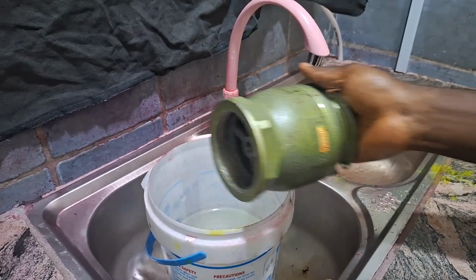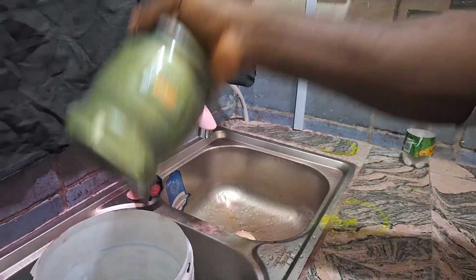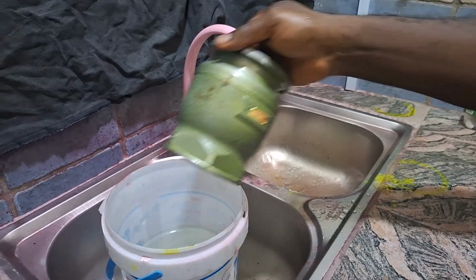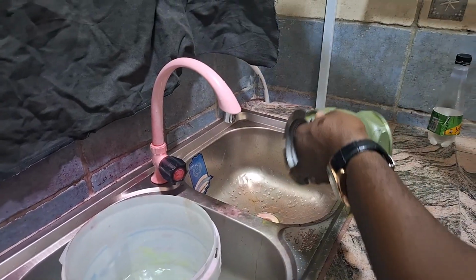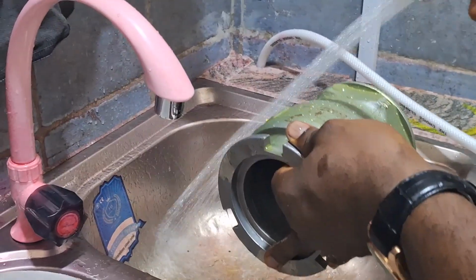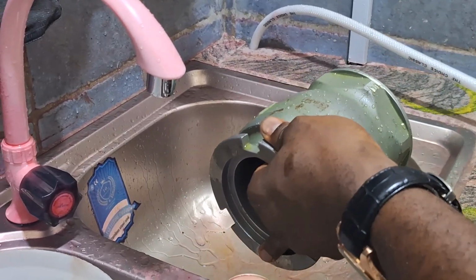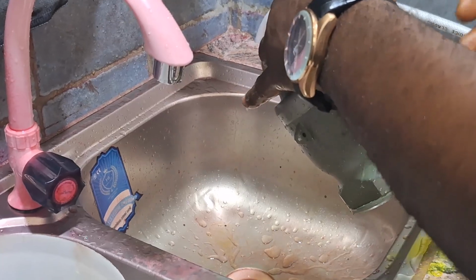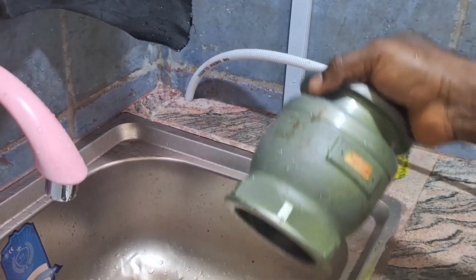In the case of your lipophilic, you are applying the penetrant. After the dwell time, you put it in your lipophilic emulsifier. The same time applies. After removing the excess penetrant, then you now use water. After emulsifying, you now use water to remove what is left of it. Take note, this is not being done properly. This is just an illustration. If you want to do it real, you see that a lot of this will be taken out. All the penetrants will be taken out.